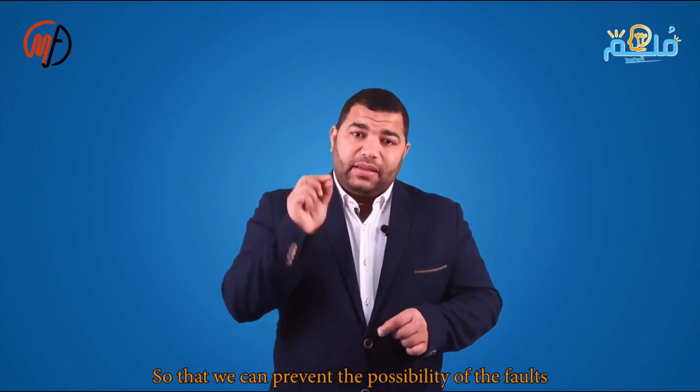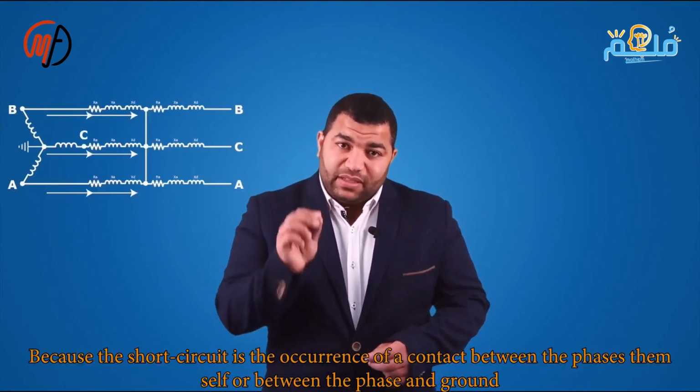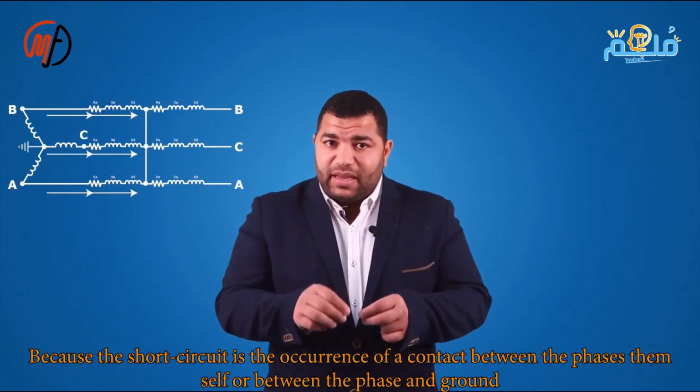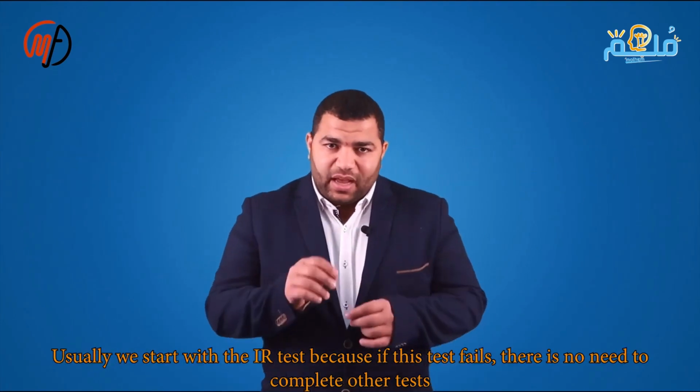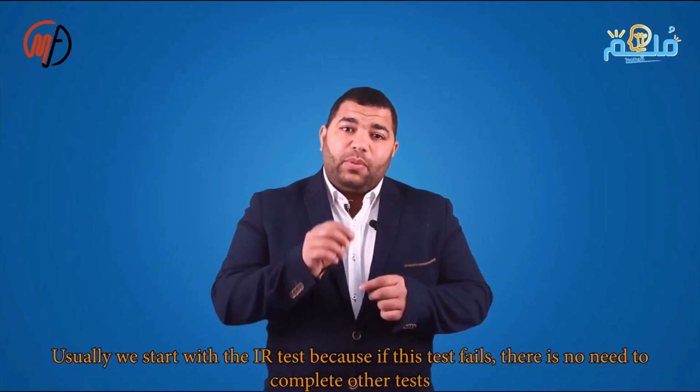First is the hypot test. Perform the IR test before and after the hypot. Note, hypot is for the power circuit, primary side only, and you discharge after each test. We start with the IR test. If it fails, CT tests are unnecessary as the CT would be rejected.